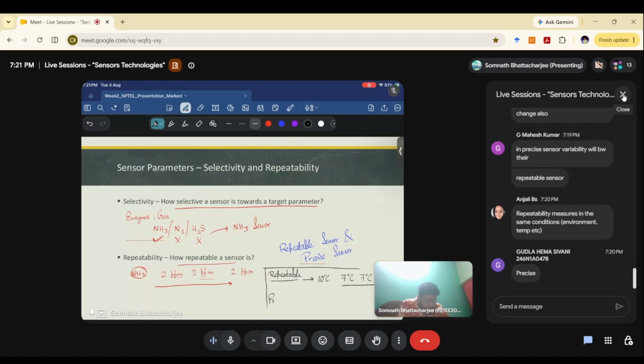One. So we are not entirely talking about 1, but this is less than 1 degree. So resolution is less than 1, right? No, not 2 millivolts. The resolution is the amount of smallest detectable change. So always resolution will be in terms of the input values, right? So our input was this, our output values were this. So based on this, the resolution was less than 1.